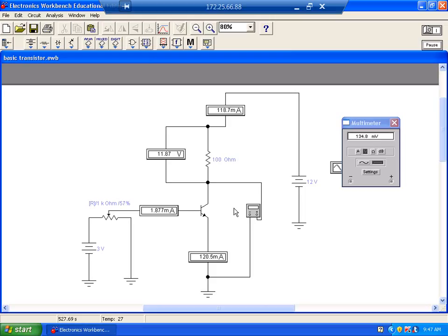So we're going to have two currents. We're going to have two measurements that we're going to deal with. And one of them is going to be called IC max. The IC max rating is the current you can get through the transistor if it is saturated. And then we're going to get a power dissipation. As soon as I have my transistor drop a voltage, then now all of a sudden it's consuming power, right? You understand?